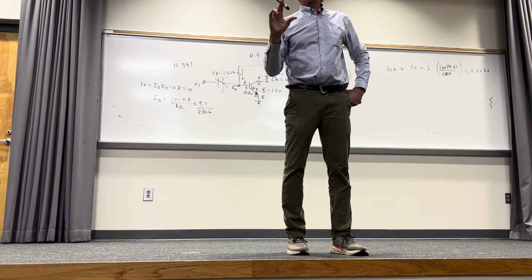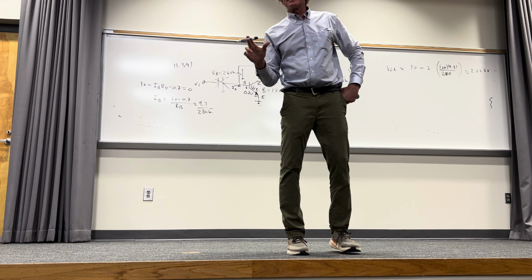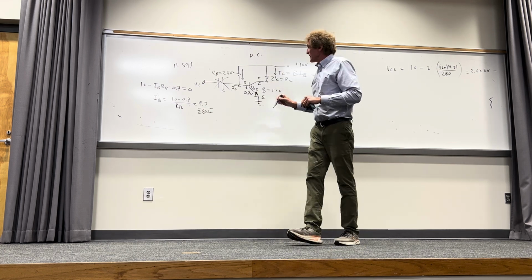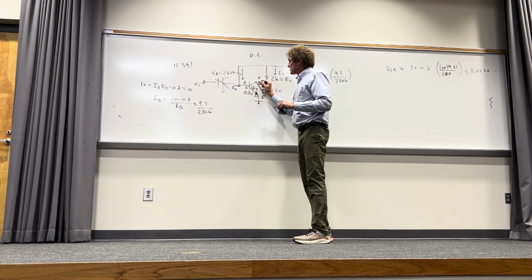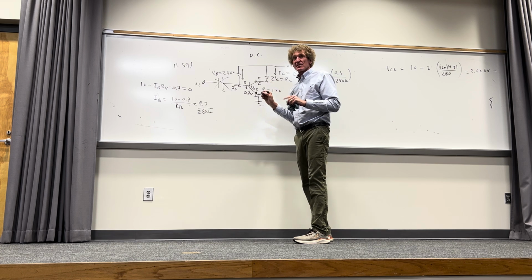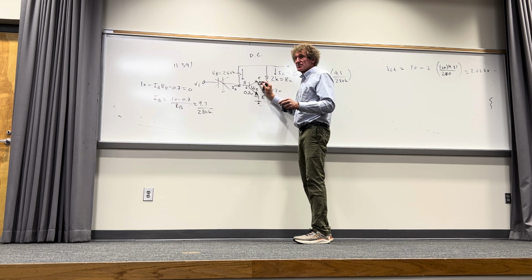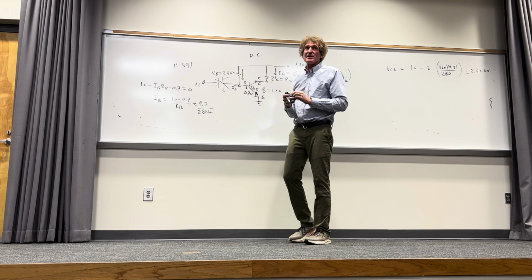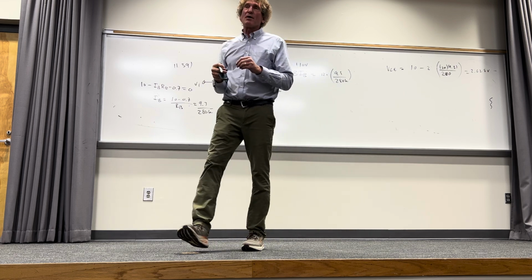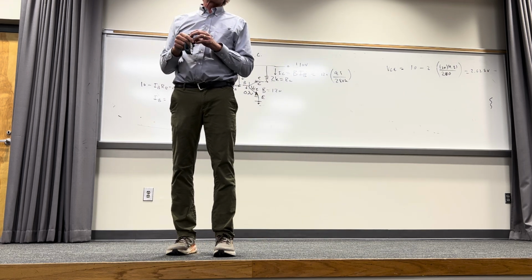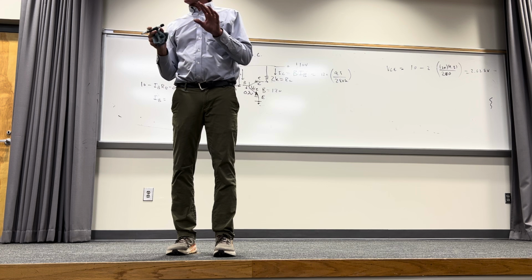The way they get it is, they assume that this junction right here, this is another diode effectively, is going to be on almost, hear me on this one? So almost 0.7 volts, you should get ideally 0 volts there, but you will get somewhere between 0.1 and 0.3, typically 0.2, you said, right? And I'll get to that more.